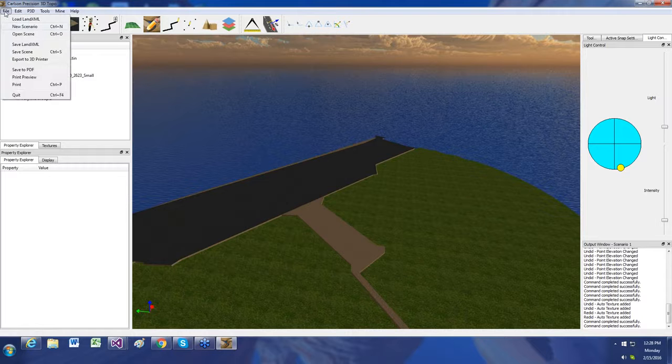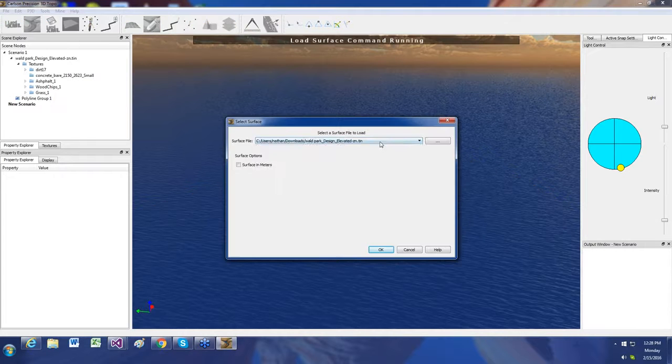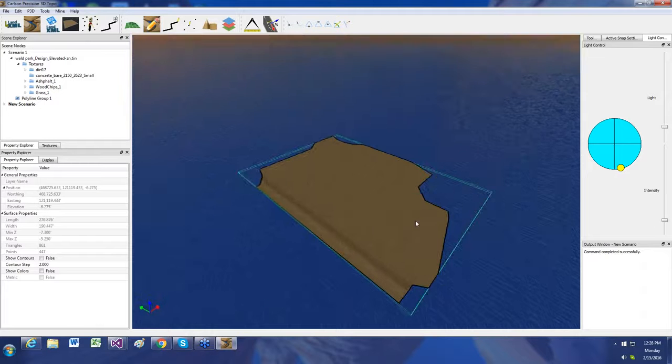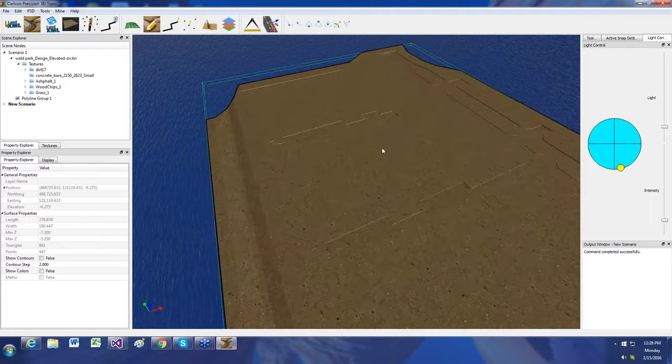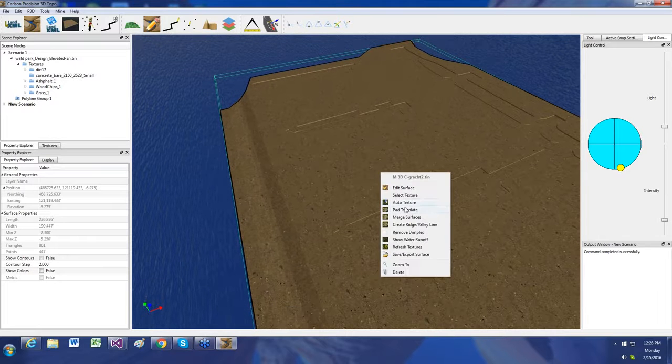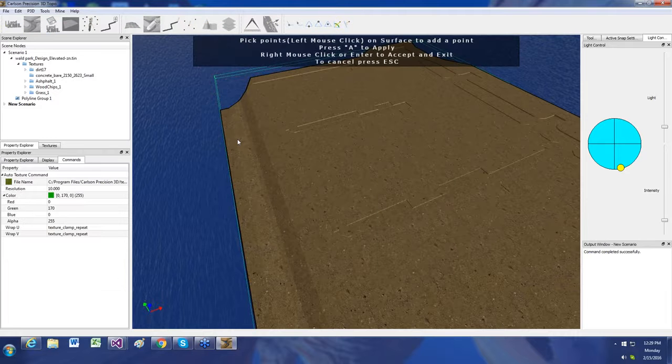I'm just going to start a new scenario here really quick and load a different file, an international file from Holland. Lots of flat stuff going on over there. So really quickly, what I'm going to do is texturize this. So this is typically what you're going to find of a LandXML 1.0 file coming from any other company until more adoption is there for LandXML 2, which supports all of these textures and colors embedded within the LandXML file. So you don't actually have to ship the images that are textured as well. They're actually all packaged in the LandXML file using standard XML techniques.